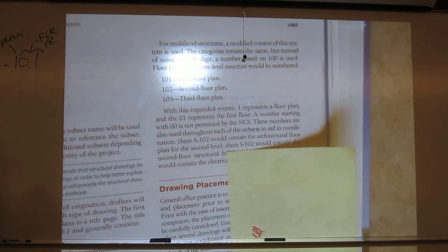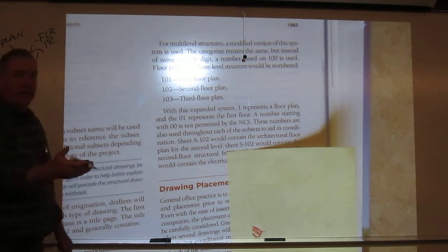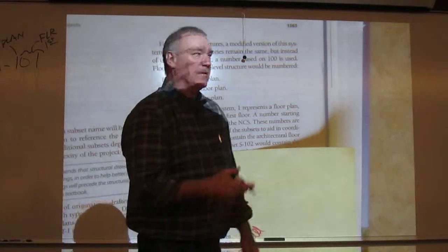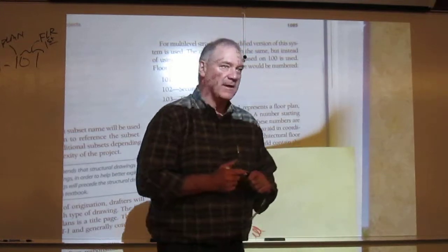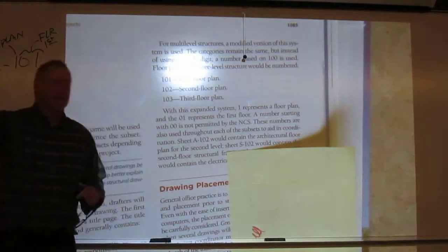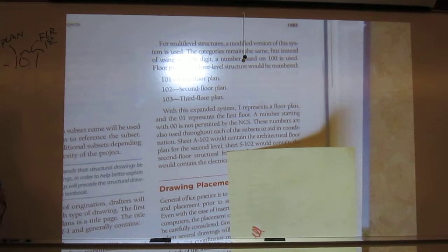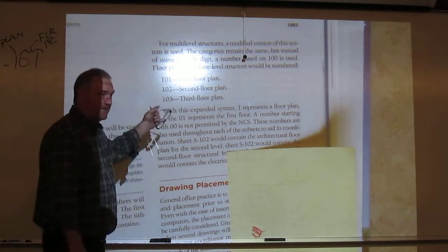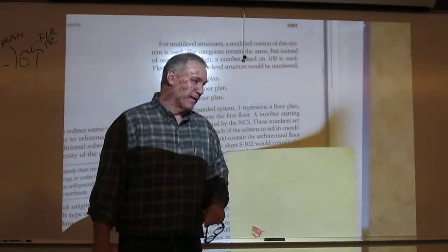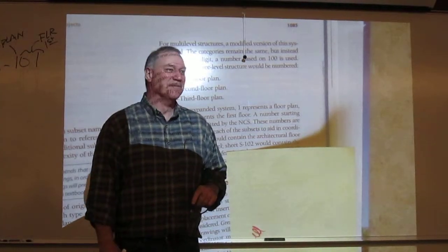Okay. If I saw an A102, I'm looking at an architectural floor plan of the second floor. A103 would be the third floor, and so on; for a large skyrise, this can get fairly large. And these designations all go in the sidebar, down in the bottom corner for your drawing number. And generally in these general sheets, there's also a table of contents.